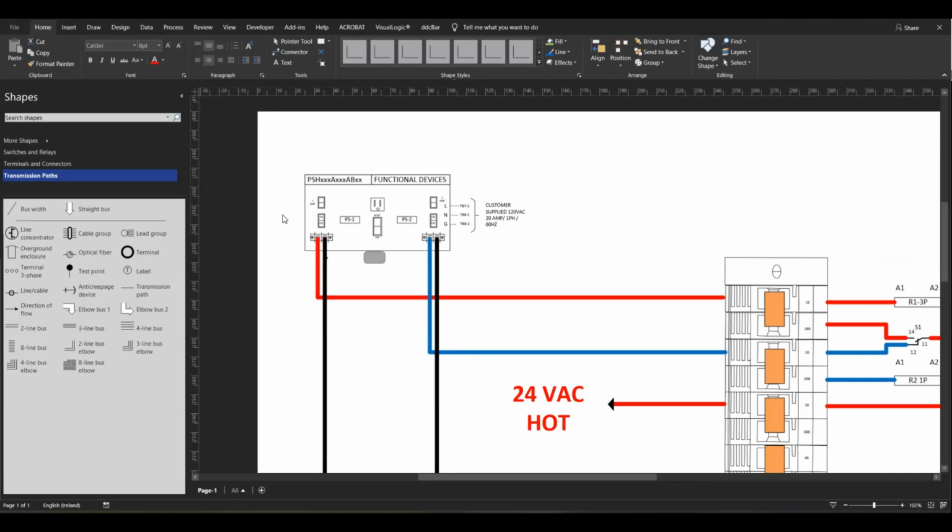a dual power source. So you could use two single transformers, or the power source that you are using just has to be two sources, which can convert 120 VAC or 220 VAC to 24 VAC for the BMS controllers, or any PLC controllers that can accept 24 VAC.